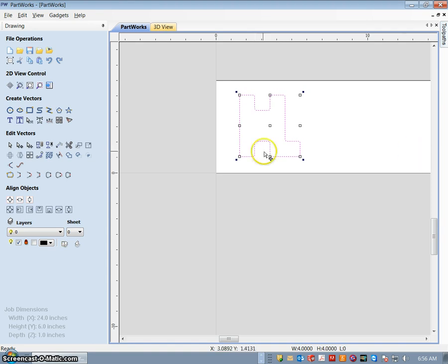Now we're going to have some hold down clamps on the shop bot right about here. We also want to have some space right about here. So this is where we're going to pull our parts in. You're going to then bring the rest of the parts in and create a layout that allows you to create your toolpaths.